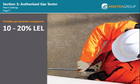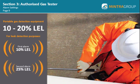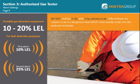For leak detection purposes, in other words not process monitoring, the first alarm level should be set as low as practicable, preferably no higher than 10% LEL. The second alarm level should be no more than 25% LEL. Do not confuse percentage LEL with percentage by volume in air. 20% methane by volume in air is a dangerous level, which could quickly creep into the explosive envelope.